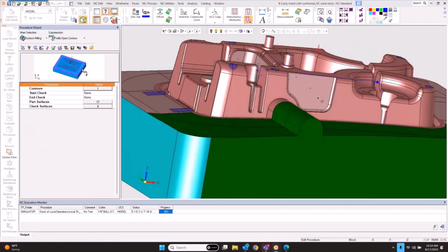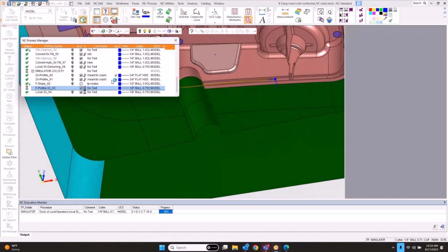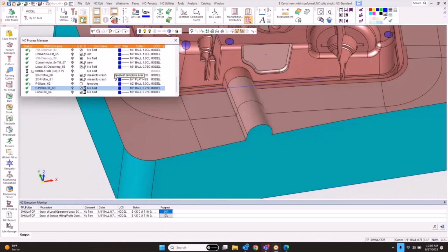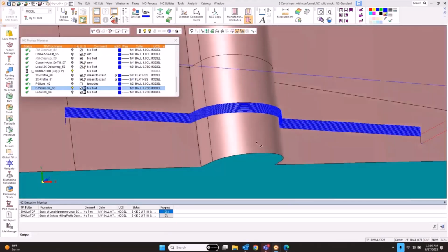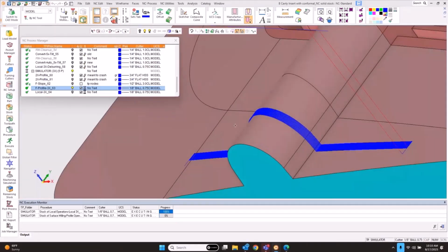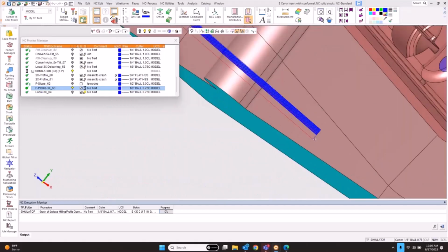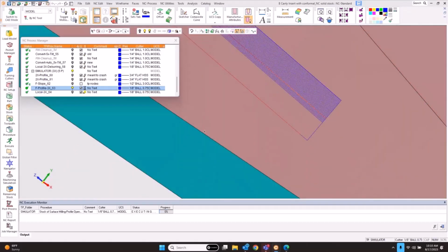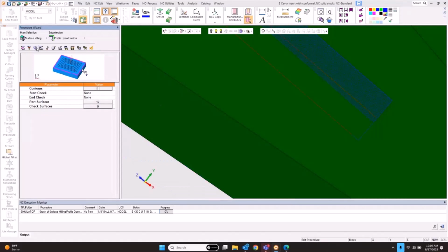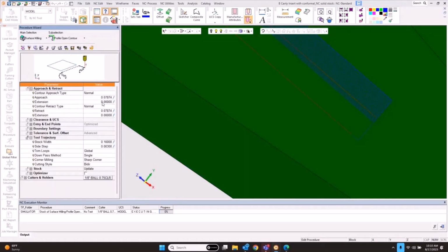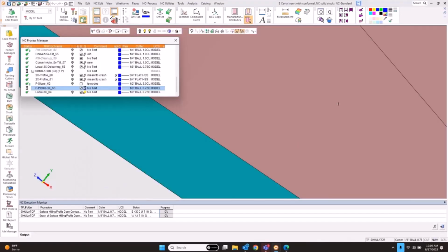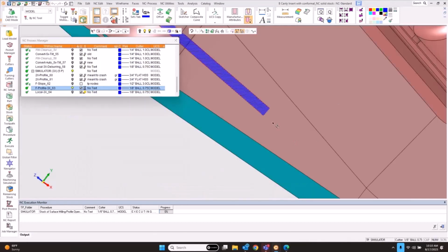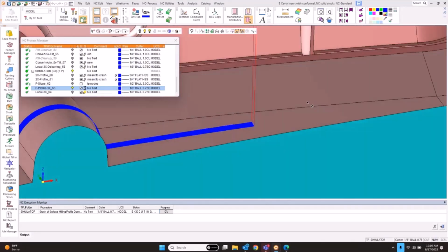So the curve doesn't actually have to lay on the surface, it just has to project down. That's probably more what you were looking for. Just remember that it is a profile procedure in the background. So keep in mind the approach and the retracts, normal, normal, or tangent, tangent. I'll go ahead and set those to 0 so it doesn't start over here and leave a track on the part. And that's sort of how I would go about cutting it.